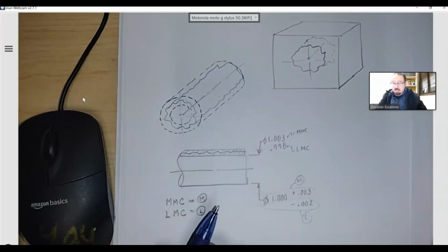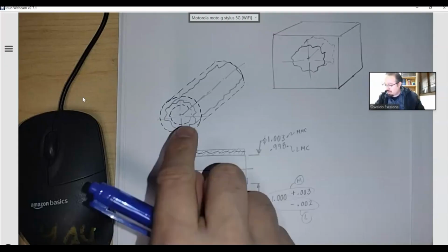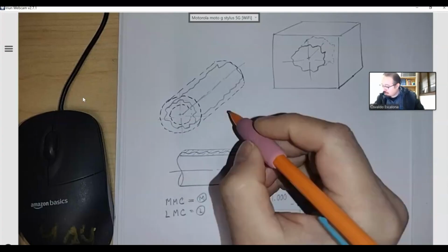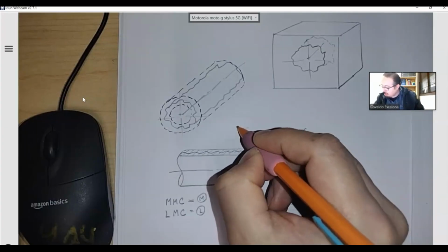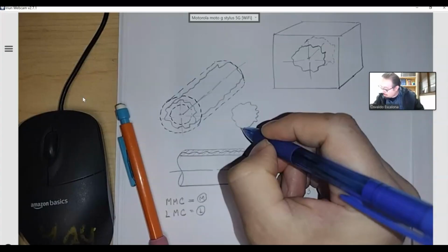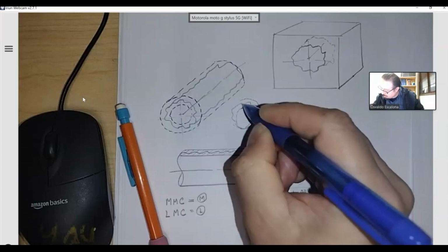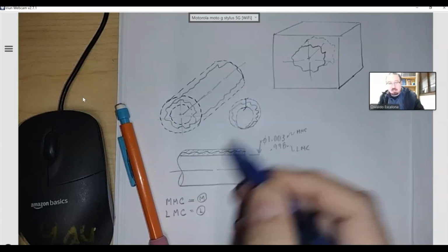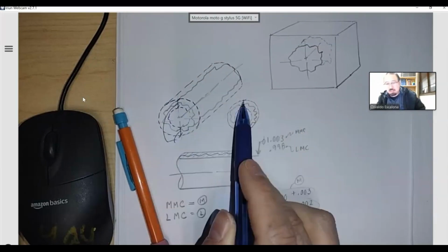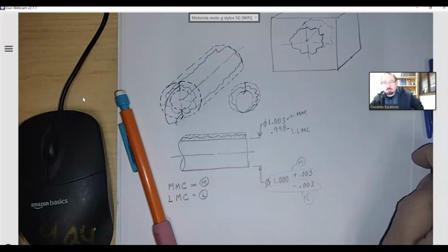And to make it mathematically easier to calculate and understand, I usually like to graph and make the bottom perfect. So pretty much I graph the hole and I shift it sideways so all the tolerances get to be on the top. So it will look something like this. I will make it perfect on the bottom, and then I make it wiggly, right? And then I grab my tolerance zone, and I push everything on the top. Right now I have a little bit on the top and a little bit on the bottom. And again, I am putting this guy and that guy, everything on the top, so it will look like this. And again, it helps because it makes it mathematically easier to understand, especially on the math, right?